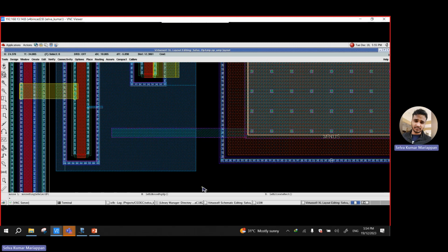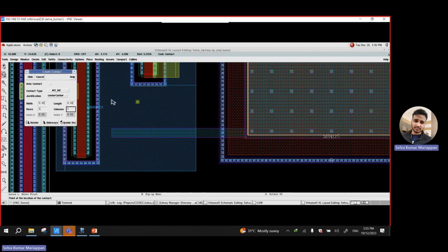So now we must go up to metal 1. Metal 5 to 4, 1 via. 4 to 3, 1 via. 3 to 2, 1 via. 2 to 1, 1 via. So we have 4 vias in total. So we do the same. From the top, metal 5 to metal 4. And I have a big one, so I can just put 6 rows, maybe like that.